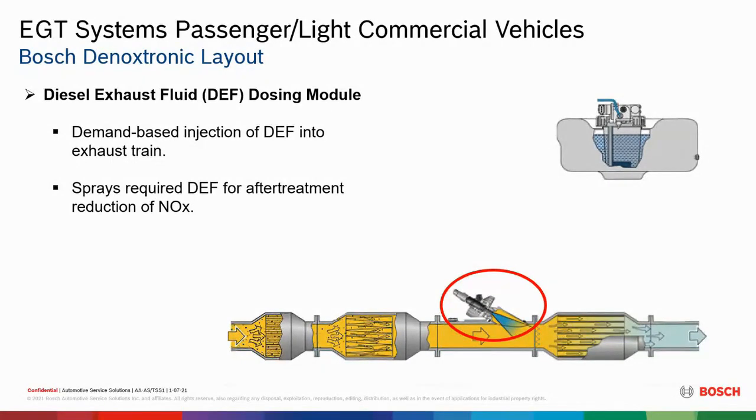But you got to replace the dosing module, because if it's not spraying properly. And I'll show you how to test that as well to get an idea of if it's atomizing properly. It's not the easiest thing to do when it's working right. You can't really tell because it's atomizing, but when it's not working right, believe me, you'll be able to tell that the injector is partially plugged.